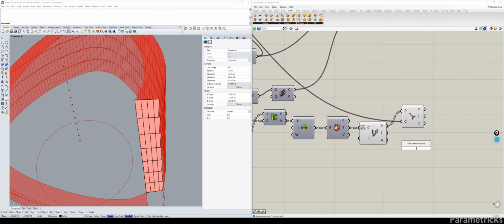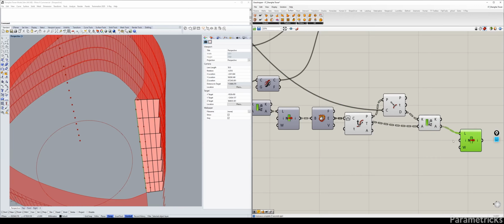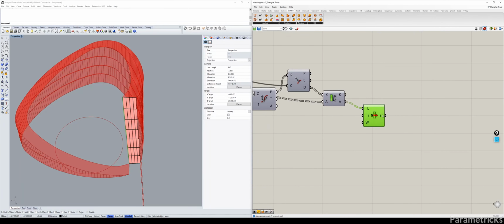With that said, we can now sort the distance with synchronizing to the line, and then the same thing, we can now select the lines, because we know these lines are going to be the shortest to that center line that we selected. So now all we do is flatten this and then join curve to create a single polyline.